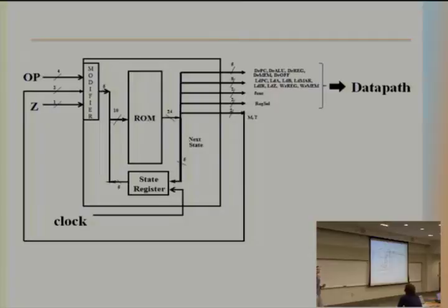So for example, if you didn't have any branching in your code, then basically these 2 bits will overwrite all these additional bits that we added, and they will be just plain zeros, and we'll have 5 zeros and 5 bits from the state register, and that will be your address in ROM. But if you did have any branching, then all these extra bits will kick in and basically determine what will be the address.